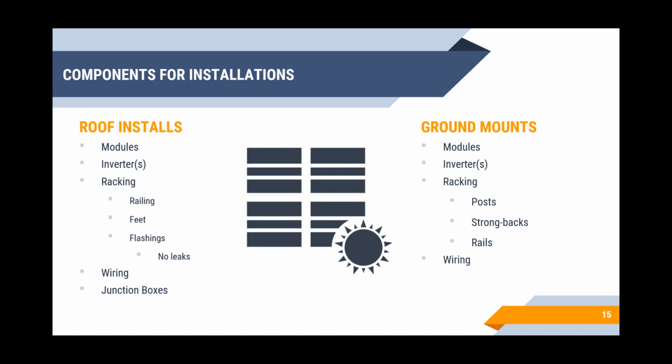And just real quick, on the different places for microinverters and string inverters, and why we use string inverters on ground mounts. The way microinverters work, if one panel gets shaded on that array, that's not going to bring down the entire array because you have multiple other panels on multiple other inverters that are still producing energy. Whereas with the string inverter, if one panel goes down, that can stop production for that array if one panel gets shaded out. But on the ground mount, you typically won't have that because you have those nice open spaces for your installation location, so it's not as much of an issue there.